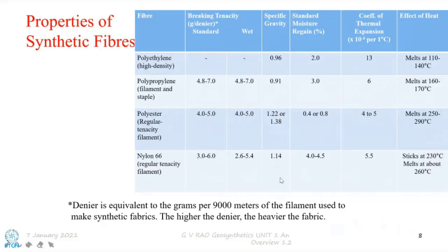When you make a product with polyester, you want to do some underwater work. That means you want to dip this geosynthetic in water. Naturally, this will automatically keep settling, whereas this is going to naturally float in water. So this we have to remember. During construction, we have to see that.